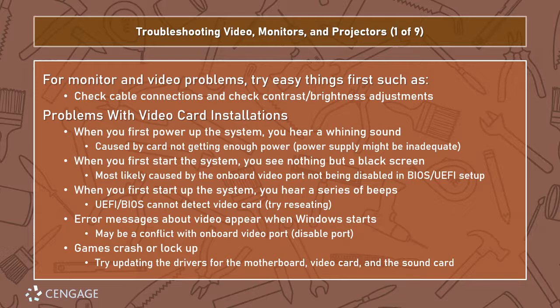Like with most things with your power supply, if you hear a whining sound, it may be that you have a card that's not getting enough power. Let's say you just upgraded and you didn't upgrade your power supply. You may be running into that issue. If you get a black screen, no display, it could be that the card is in a slot that can't support it, there's not a power connection where there should be, or the onboard video is still giving you issues.